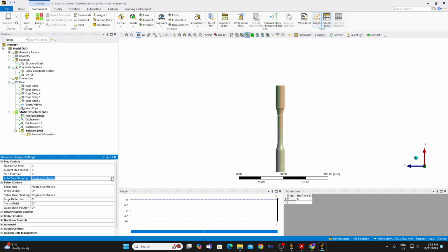And we need to change the time stepping. We would turn the time stepping on, and since we are doing elastoplastic analysis, this is what I would suggest. You see, we are talking about 30% of the strain, that is 0.3, and the elastic region is only 10 to the power minus 3, that is 1 by 300 of that.